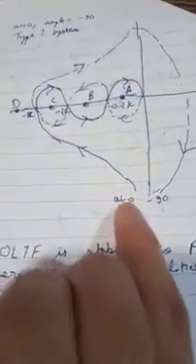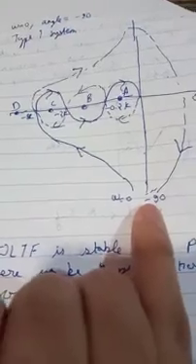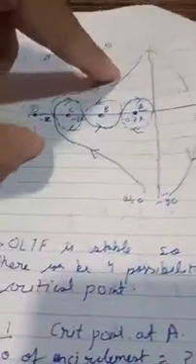And this Nyquist plot starts from omega equal to 0 at angle minus 90 degrees. So we can say that it is a type 1 system. So I have drawn the polar plot for this by using the mirror image. So this is the mirror image. And this is the circle. Since it is a type 1 system, there will only be one circle.